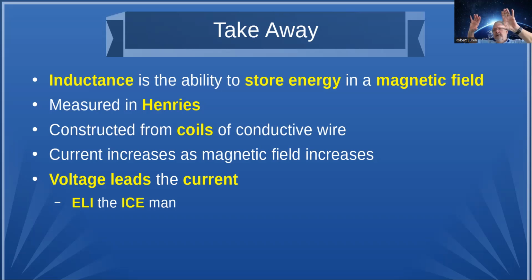So you're going to transfer that energy in the capacitor completely over to the inductor. The field in the inductor at some point is going to collapse and recharge the capacitor. So you're going to have that energy moving back and forth between the inductor and the capacitor. And if there's no loss, it would sit there and oscillate forever.